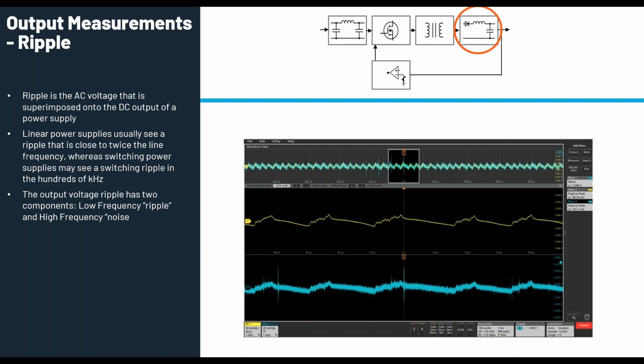You need very accurate probes and a testing system to measure that, because it's not very easy. It can be at the level of millivolts or microvolts depending on which kind of circuit you're working on. So accurately measuring that is a challenge. We will talk about how we can measure that accurately and see more into the microvolts level of ripple.